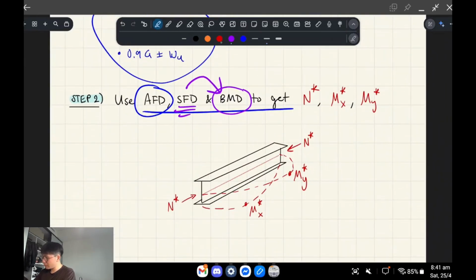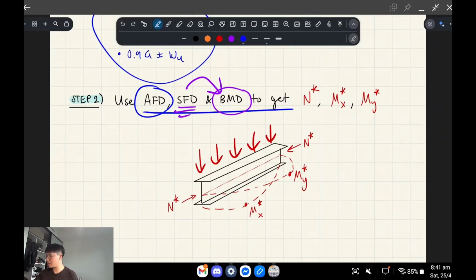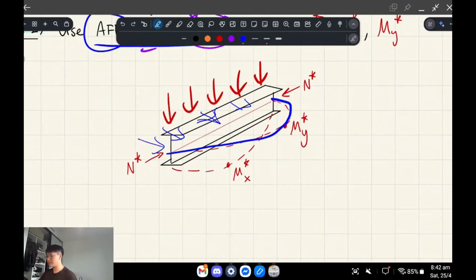Sometimes, for example, so let's say this is a beam, right? But this also applies to columns, right? If you've got vertical loading on a beam, you basically get this one. So you would have bending in the XX direction, but also if you have wind loading, for example, right, off to the side of this beam, your bending moment actually, like the beam wants to go sideways, right? So the bending moment diagram, you would actually map sideways, and that would be MY. So the reason it's MY is because it's bending about the YY axis, okay?